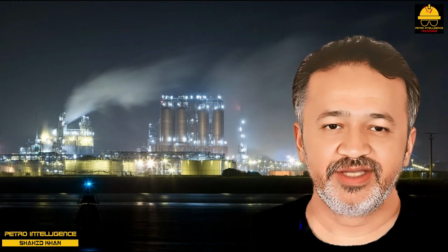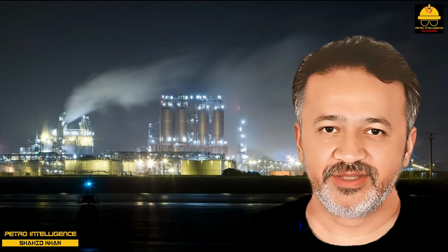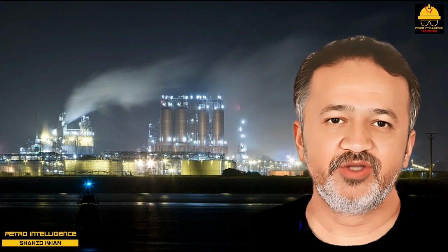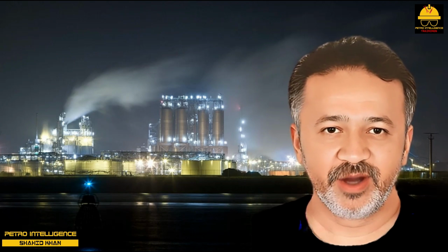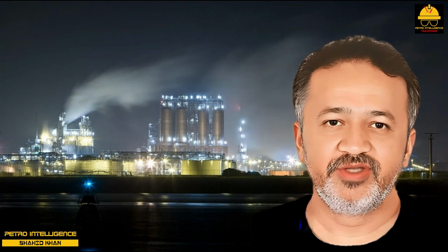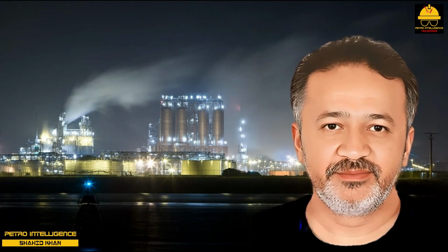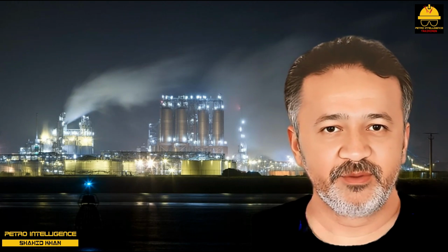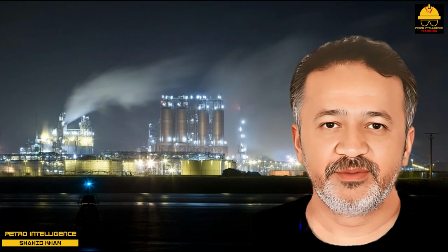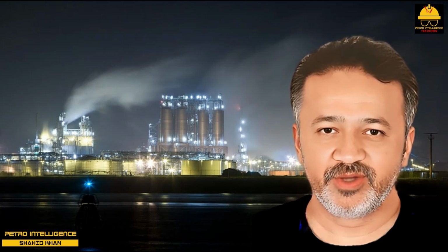Impingement plates and seal strips. The shell side impingement plate must be a bit larger than the inlet nozzle to protect the upper rows of tubes from the erosive action of the shell side inlet fluid. To accommodate the impingement plate, several rows of tubes must be omitted along the top of the bundle.